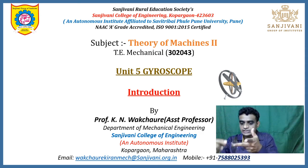And about that axis the whole body moves either like this or like this. There are three axes. This is the axis of spin. The body which rotates about this vertical axis is called the axis of precession, and that is the gyroscopic effect. Because of that gyroscopic effect, the whole body will rotate about the third axis, which is called the axis of gyroscopic couple. In this way we have to study the gyroscopic principle.